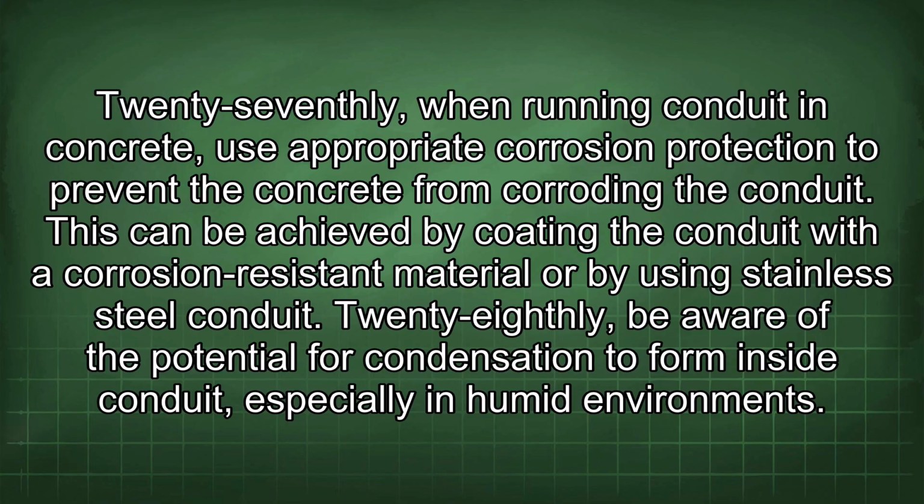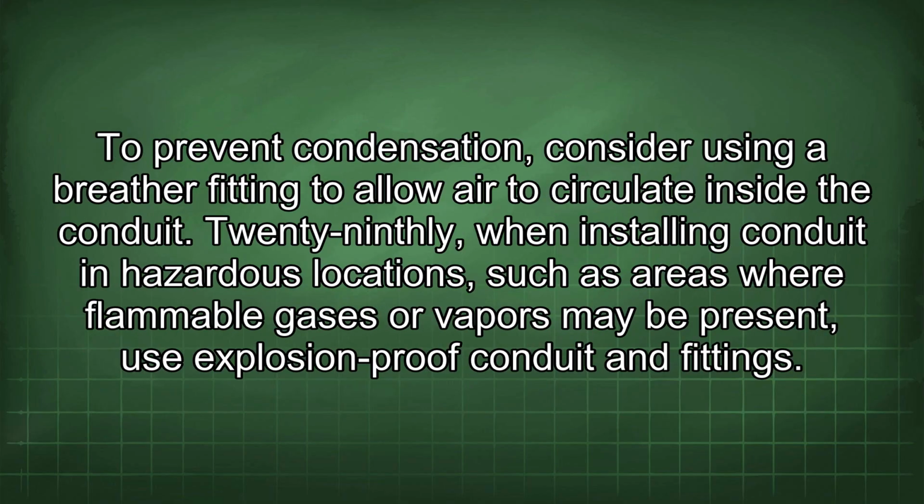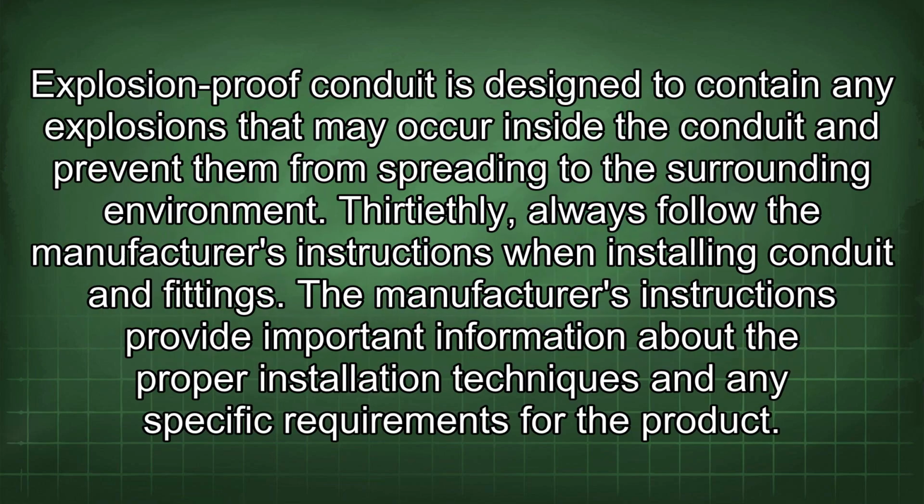28thly, be aware of the potential for condensation to form inside conduit, especially in humid environments. To prevent condensation, consider using a breather fitting to allow air to circulate inside the conduit. 29thly, when installing conduit in hazardous locations, such as areas where flammable gases or vapors may be present, use explosion-proof conduit and fittings. Explosion-proof conduit is designed to contain any explosions that may occur inside the conduit and prevent them from spreading to the surrounding environment.